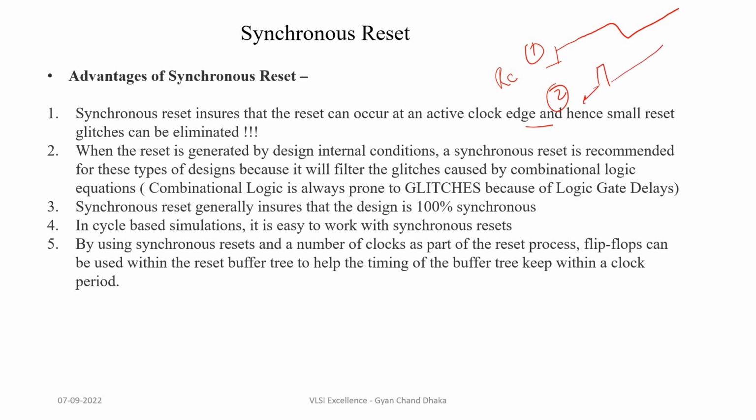This is the expected reset pulse. This pulse is long enough, and if our clock signal looks like this, at the active edge of the clock the reset pulse will be detected and our design will get reset.